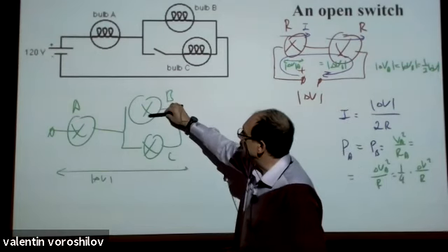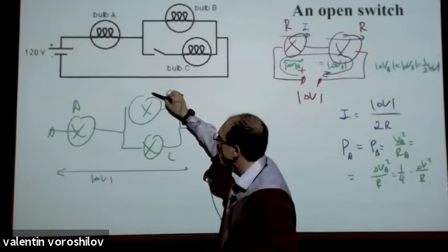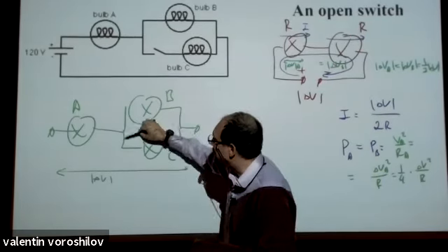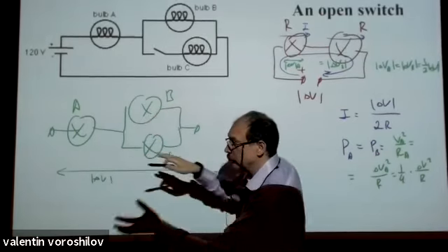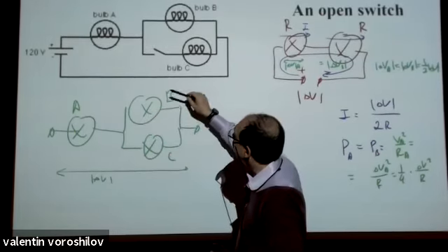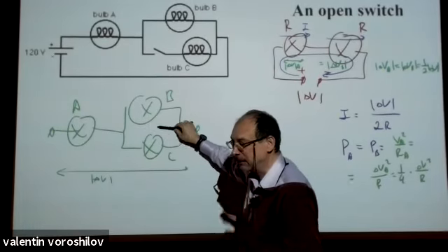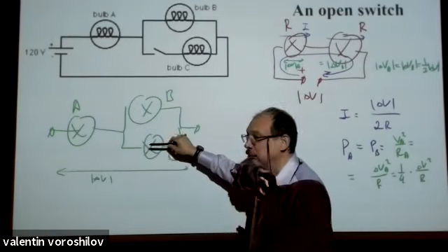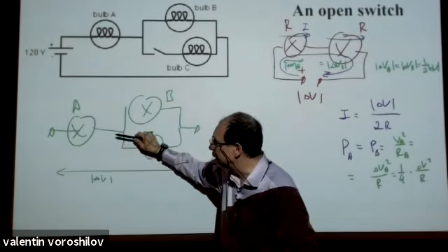By adding an extra element in parallel, we are decreasing the resistance. We give electrons more room to travel through. If we decrease the resistance of a part of a circuit, we decrease the overall resistance. When resistance goes down, electric current goes up.